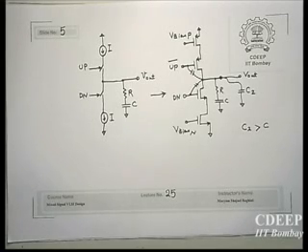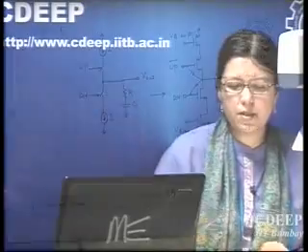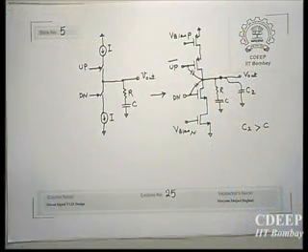But to take care of bandwidth, usually this C2 is chosen larger than C. Not much larger, say from 2 to 10 times in this range, so that you actually won't see the effect of C2 early. But it helps to reduce the effect of these spikes. Because now C2 will keep this voltage unchanged, and C2 should be large enough compared to the parasitic capacitances of the switches, so that it is the same as a sample and hold circuit. It will keep the output voltage almost constant.